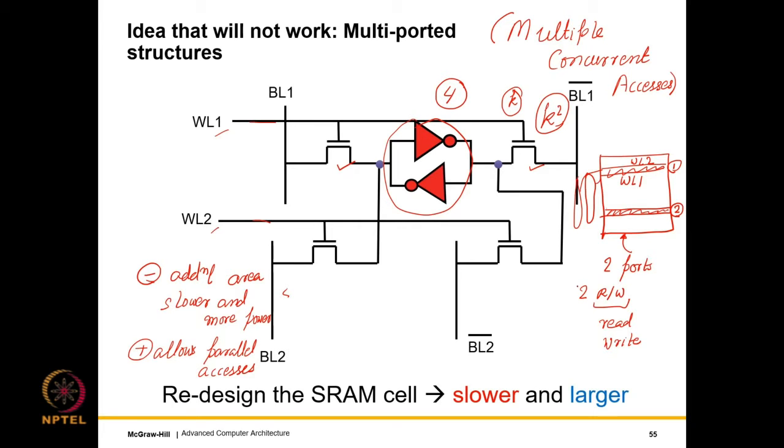So of course here the question is, can we do 2 read-write ports, or just 1 read-write and 1 read, or 1 read-write and 1 write, right? So of course there will be an area penalty, but we can slightly reduce the amount of hardware. There are a lot of choices. How do we resolve them?